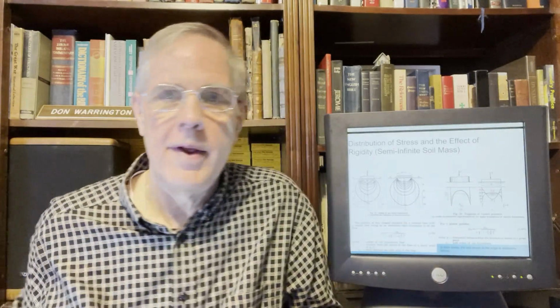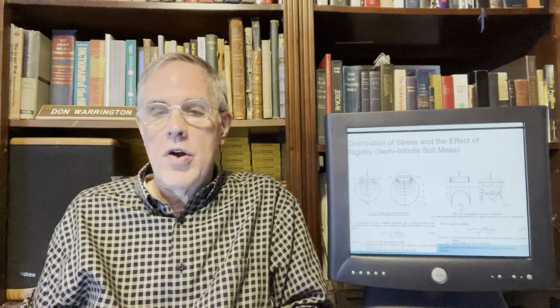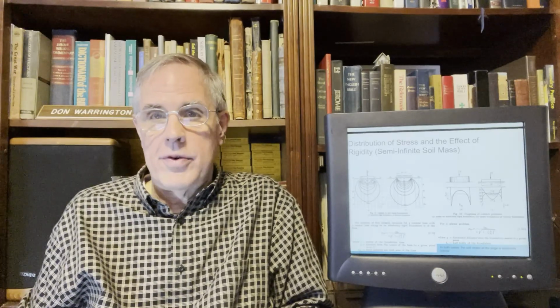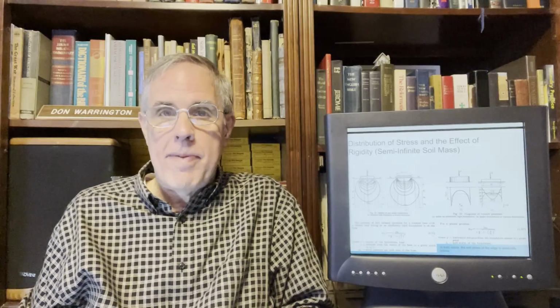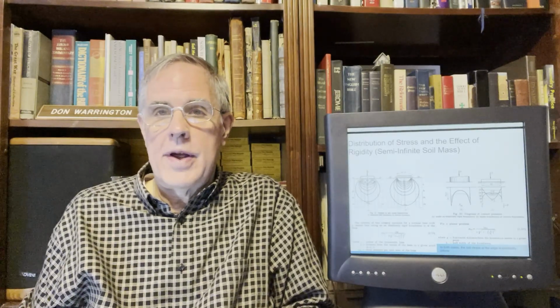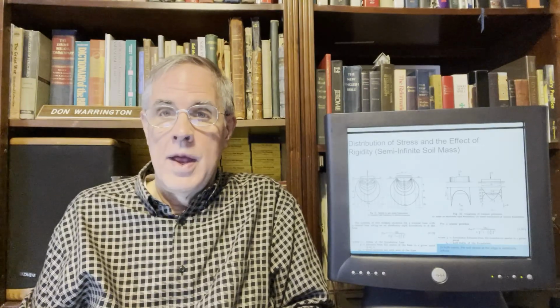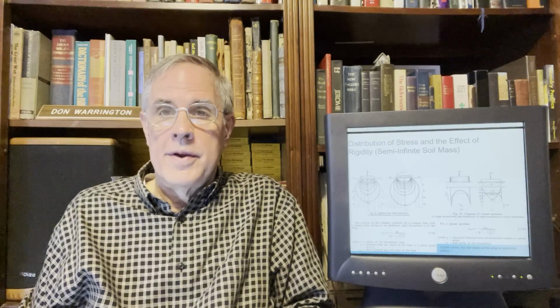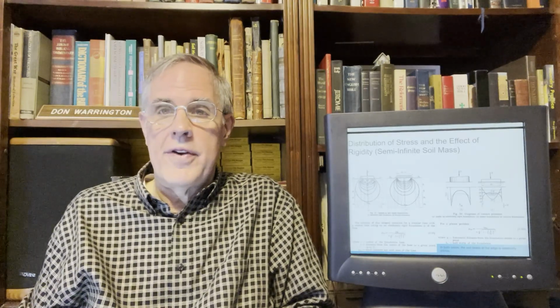You'll get a P ultimate, and the minute you put a load on there with a purely rigid foundation, what you'll start getting is plastic deformation and redistribution of stresses. Now, how bad that is or how good that is depends entirely upon what your soil is and what your situation is, or how much of it takes place. But that's the theory. And in fact, rigidity in a foundation is very important.